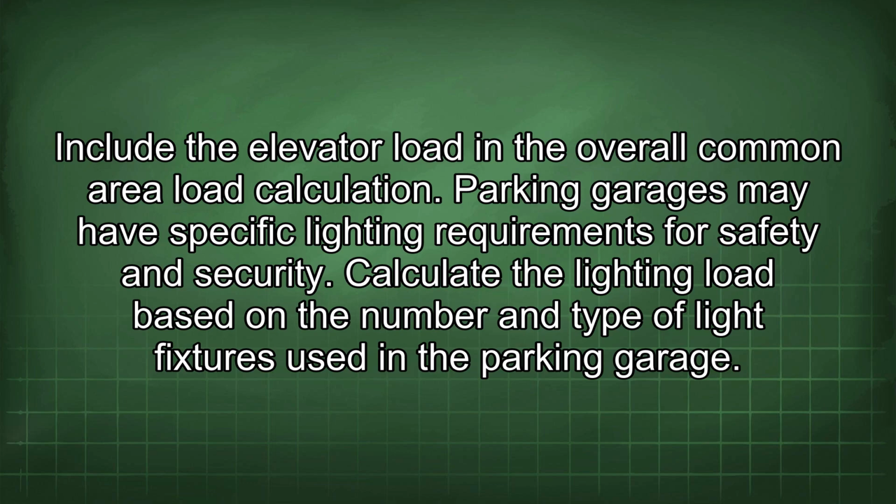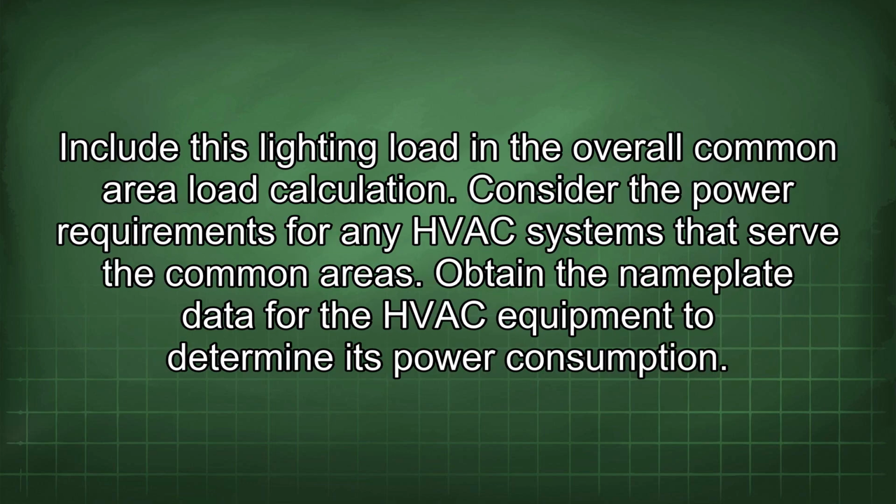Parking garages may have specific lighting requirements for safety and security. Calculate the lighting load based on the number and type of light fixtures used in the parking garage. Include this lighting load in the overall common area load calculation. Consider the power requirements for any HVAC systems that serve the common areas.